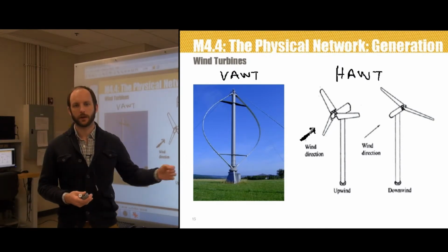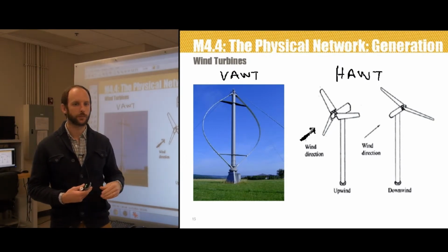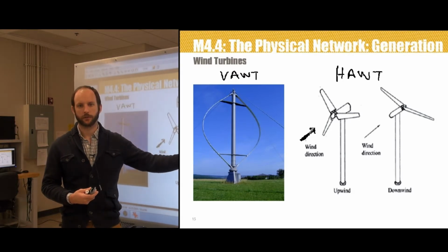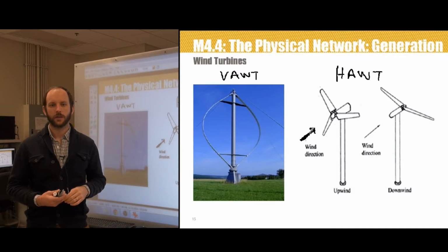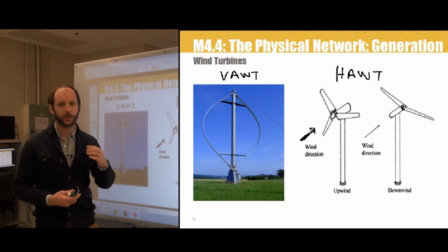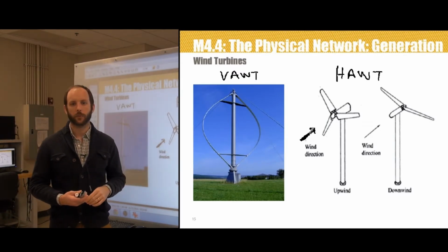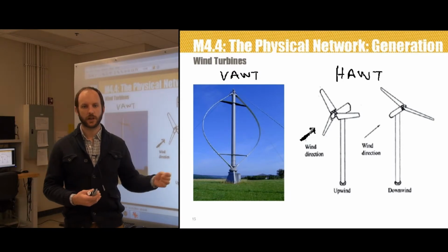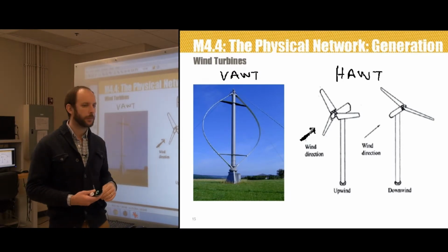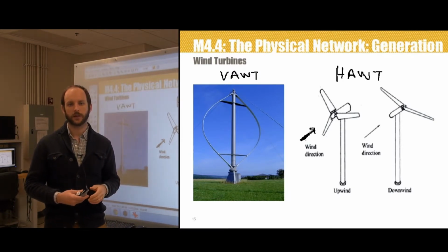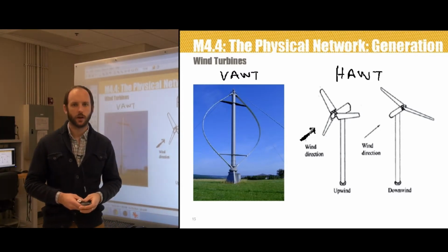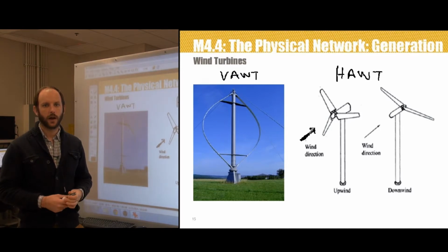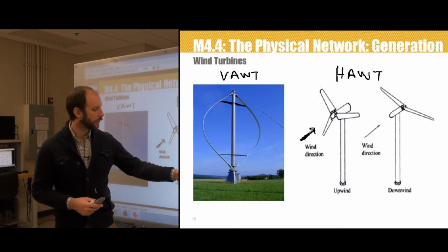The major drawback of this is the fluctuation in wind power due to the rotor passing in front of the tower and due to the effects of the wind shade of the tower. This may give more fatigue loads on the turbine than with an upwind design. The effects of the tower shadowing may to some extent be reduced by utilizing a tower design which provides minimal obstruction to the flow, so very narrow towers can reduce this effect in the downwind design.